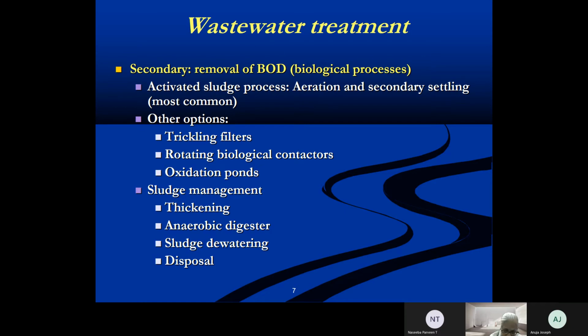We are dealing with fermentation or anaerobic conditions, and in those conditions you will get CO2 and methane. So we will come to that. There is an enormous reduction in the amount of sludge generated, and you also have the added benefit of generating biogas, which is a useful fuel. So that is the second one.